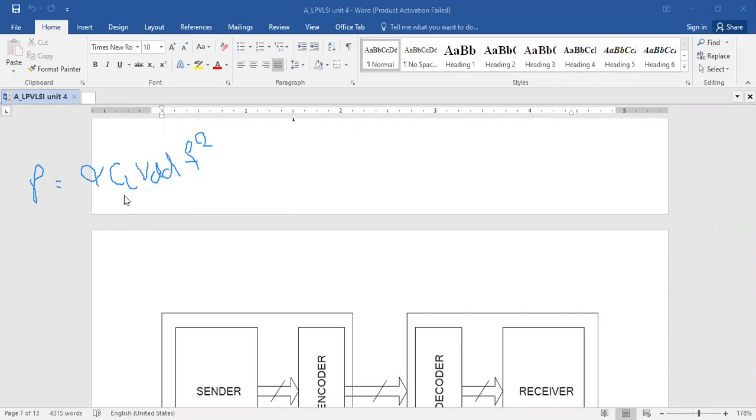In this unit, we will discuss minimizing the power dissipation, dynamic power dissipation. You need to minimize this factor. For this, we have different techniques. The first technique was system level optimization, in which you have hardware software co-design. Using hardware software co-design, you minimize the switching activity and capacitance.